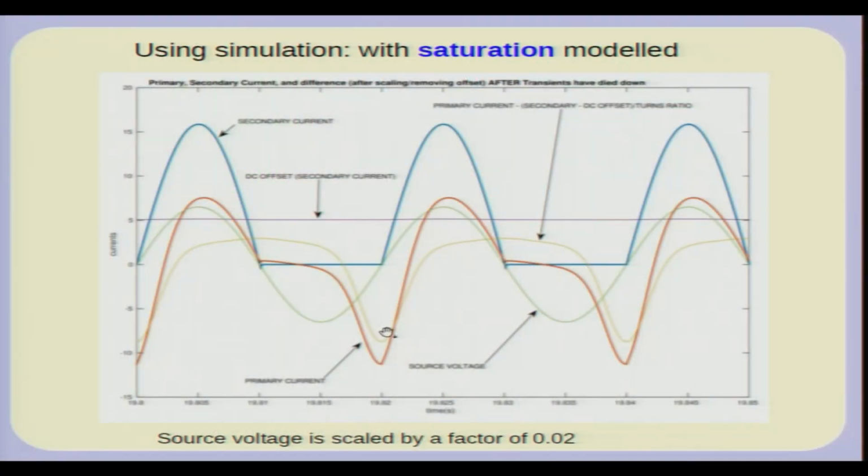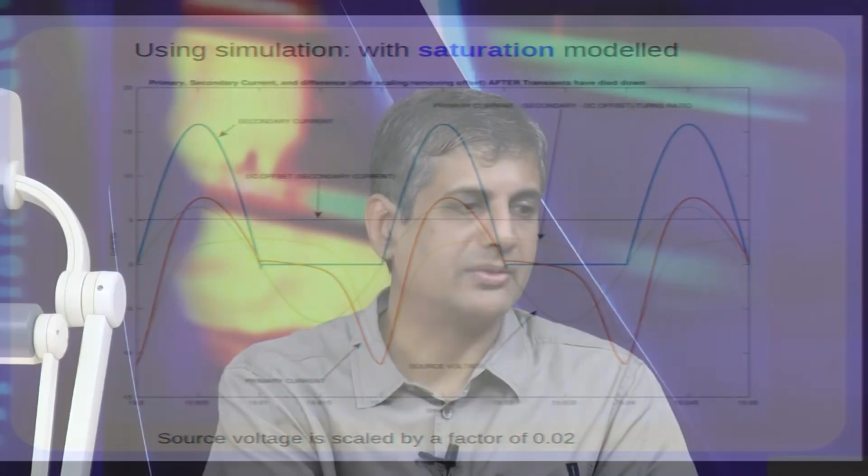I have not really checked whether the offset is positive or negative, but that is something you can try to analyze. But you go on one side, so that much is certainly true. You go on one side and because of that, on some part of the cycle, because of the nonlinearity, you require much larger magnetomotive force to set up a flux in the core. Okay. So, that is why you enter a nonlinear part of the psi I characteristic, and therefore you will find that you are getting a kind of peaky curve here. So, you can in fact do this experiment in your laboratory and also run the numerical simulation to satisfy yourself.